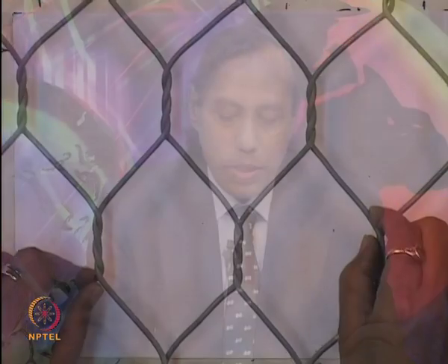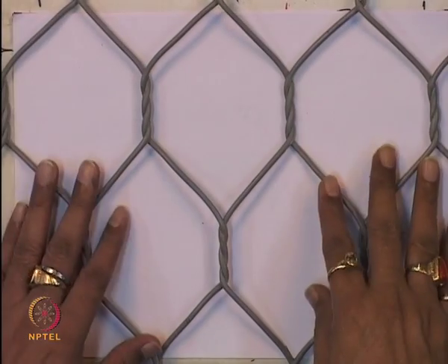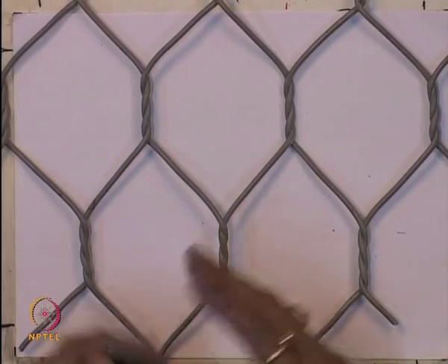This kind of design should be site specific, and you can use this material as a separator in the re-evaluation of any road, between the old contaminated ballast and the new ballast. Sometimes you also require that you remove all the contaminated aggregate, place the geosynthetics material, and then provide new ballast material or new aggregate. So this geosynthetics material acts as a separation function, a filtration function, and a drainage function, and geocell or gabion type walls can also act as a confinement function.